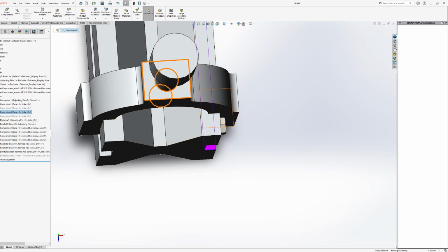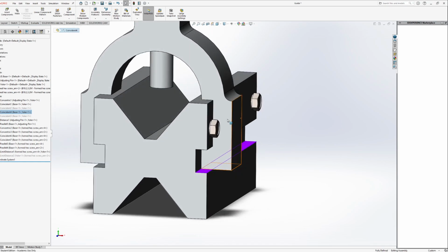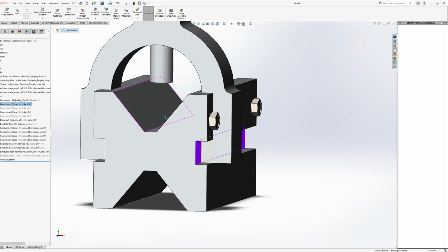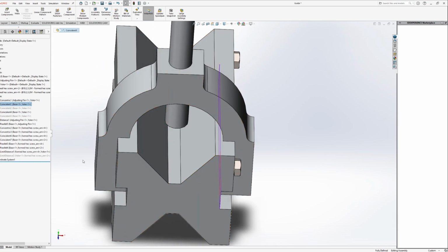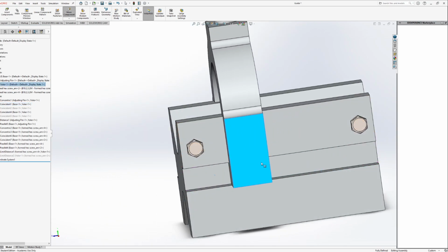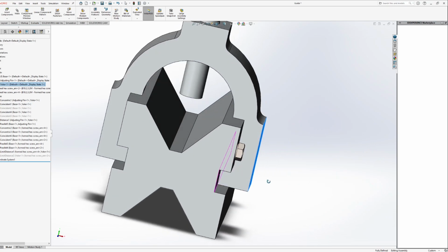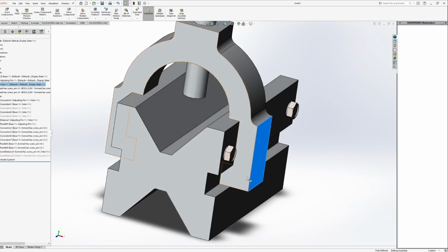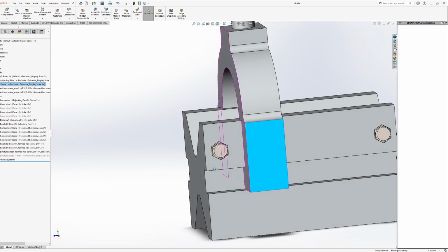And it can also move left or right, up and down from this view here. But in conjunction with this other coincidence, it now limits the direction. In fact, it limits any translation other than translation that is going to be coplanar. Because coincidence is basically ensuring that those two faces or edges or whatever geometry you have there are glued together. Or maybe not even glued together, that might be a bad word, but more so they are touching each other. They have to be right up against each other, just like how things that are coincident in a sketch are right abutted next to each other.